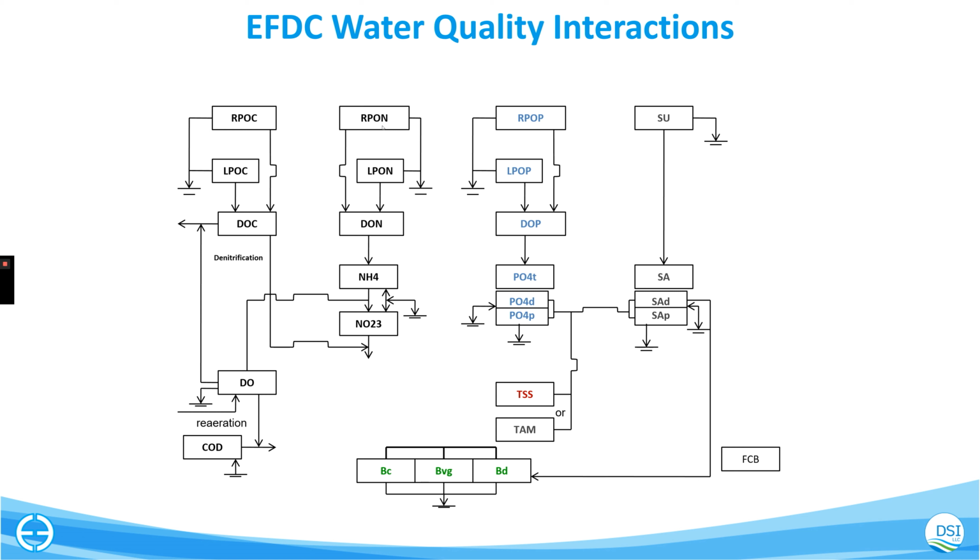If anybody is familiar with that simple analytical water quality model, you could build it with just these two, parameterize your COD as your BOD, and have your BOD interacting with DO. You can get DO sag downstream, because the model by default simulates all of the reaeration and decay processes. You've got temperature already there. It's a simple water quality model, but it works, and it depends on what your needs are.